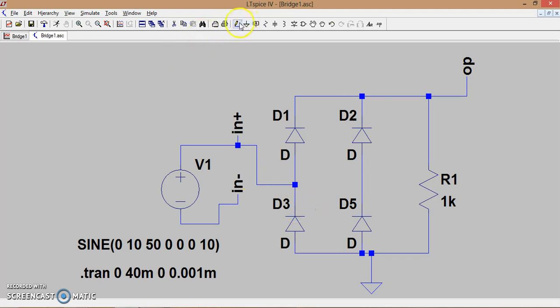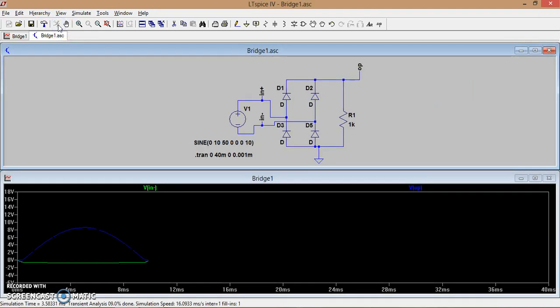You have to be a bit careful when you're running any line. Ensure that it is not crossing the edge of any component connection. Now you can see there is no node created. There is no dot here, so there is no connection. Let me run now and see whether the output is okay. Now we can see everything is fine.